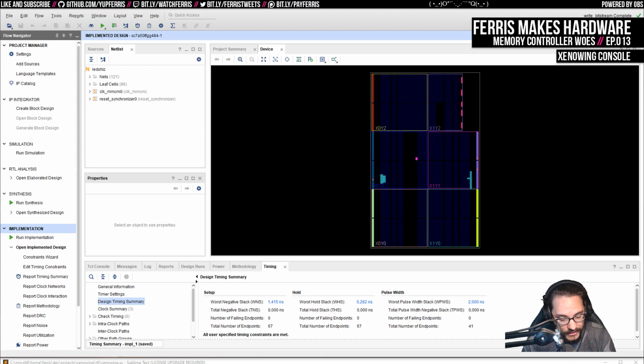And so the particular board that I have here is the Max 10 development kit. There are examples on Intel's website, because Max 10 is an Intel FPGA. There are examples on the site about how to generate a memory controller IP for this particular board, which is really nice because you need to enter some timing information that's based on the lengths of the traces on your board and everything in order for it to be configured correctly. And it had all those settings in the example.